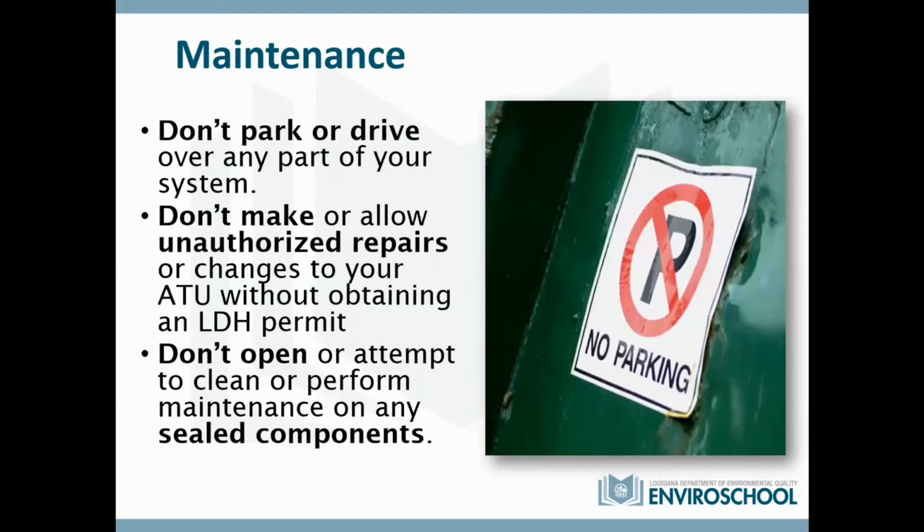It's similar to don't drive or park over the drain lines. Don't park or drive over any part of your system, whether it's the line or the tank itself. A rupture to a line or a rupture to the tank is going to cause a breakdown of the system, and you're going to incur repair costs.